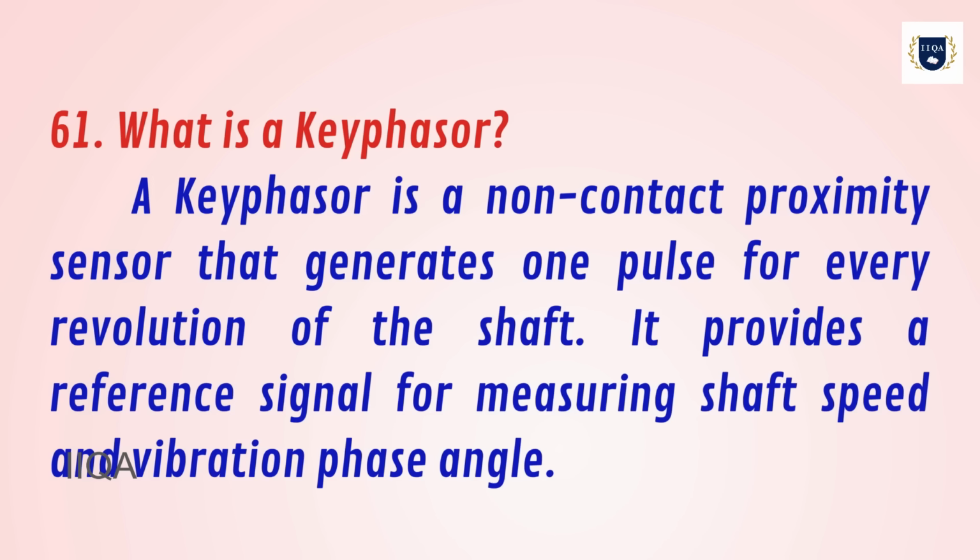61. What is a Keyphasor? A Keyphasor is a non-contact proximity sensor that generates one pulse for every revolution of the shaft. It provides a reference signal for measuring shaft speed and vibration phase angle.